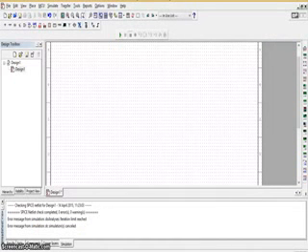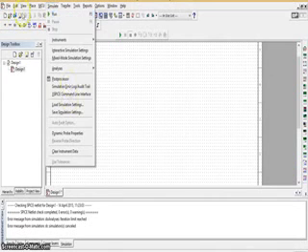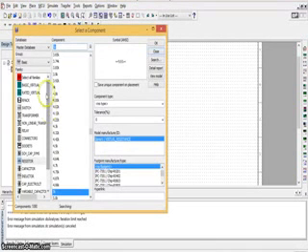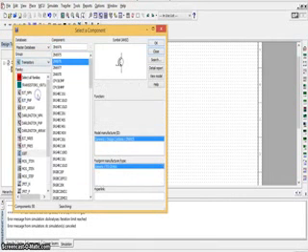Hi, this is Veerendra. Now I am going to explain the simulation of the IGBT static characteristics as my friend explained in the PPT. Now I will show you how it is working in simulation in Multisim. First we will take the IGBT. Go to get new part and select transistors. In the transistors select IGBT, and we will take IGBT as 2N6976. We place it here.